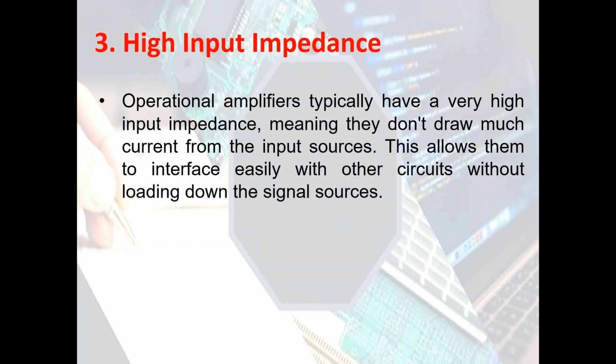High input impedance means that the op-amp presents a minimal load to the connected input signal source. In terms of the function, high input impedance prevents the op-amp from drawing significant current from the source, ensuring that the signal source is not significantly loaded or affected by the op-amp.